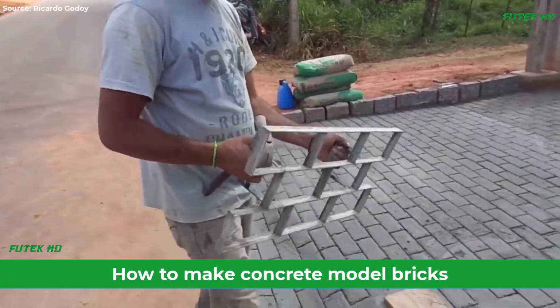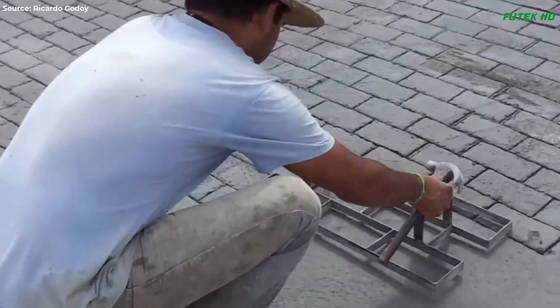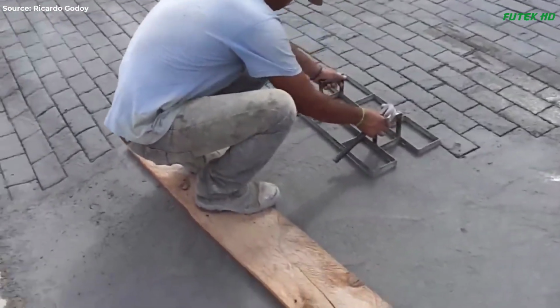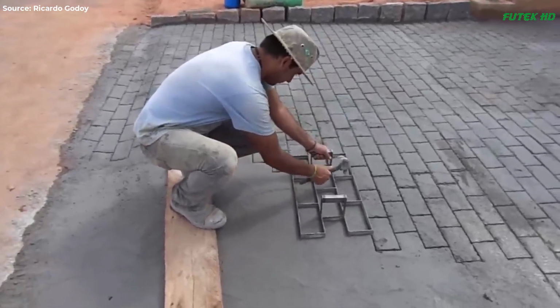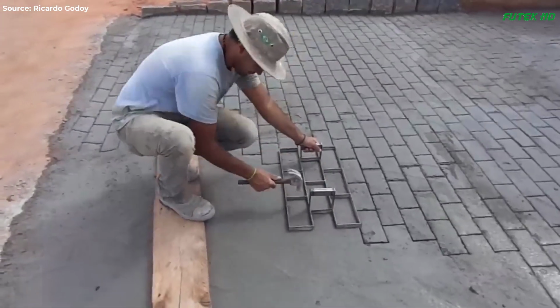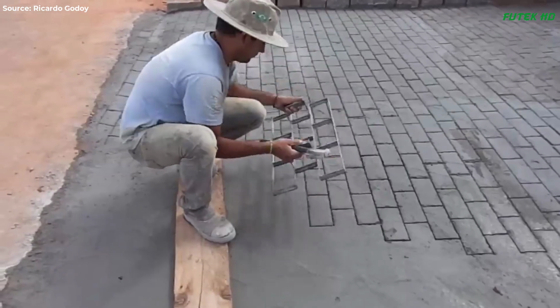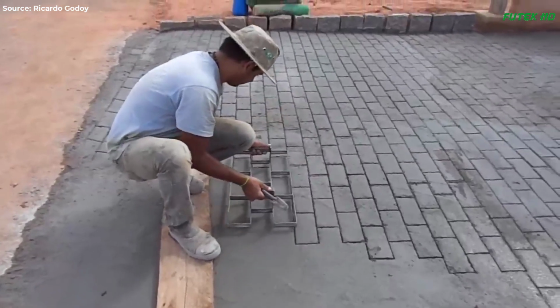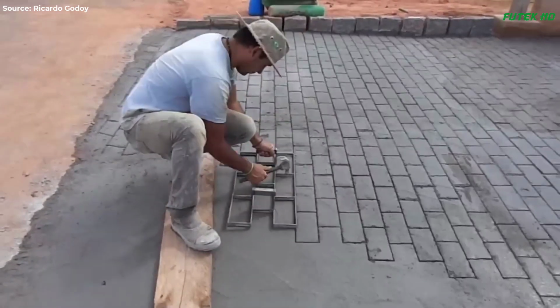This section is going to show you a simple way to make concrete model bricks, perfect for your next project. This method is efficient and budget-friendly, making it ideal for DIY enthusiasts. First, gather your materials: cement, sand, gravel, and water. Mix 1 part cement, 2 parts sand, and 3 parts gravel in a wheelbarrow or mixer.